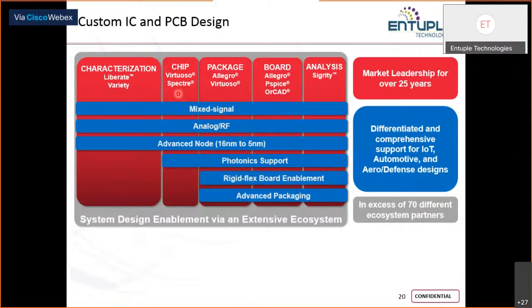And for physical verification, once the layout is complete, you'll be moving into the physical verification, right? So for that process, we have the tool called Assura. Okay, Assura and PVS is a physical verification system that helps us in working on the physical verification. So the steps we have already seen. It will be DRC, design rule check, and layout versus schematic. Okay, comparing your layout with the schematic and checking whether all the interconnections, components, and input output ports are available both in schematic as well as layout. Okay, so to check those aspects of your design. Okay, and once that is done, you will move into the packaging process. Okay, so Allegro helps you in those aspects.